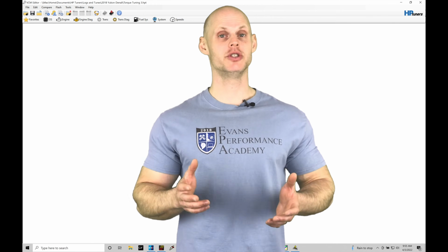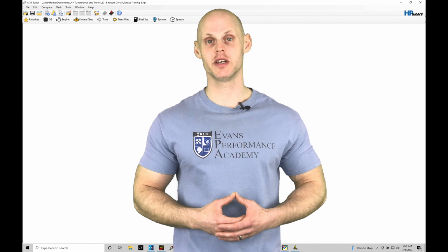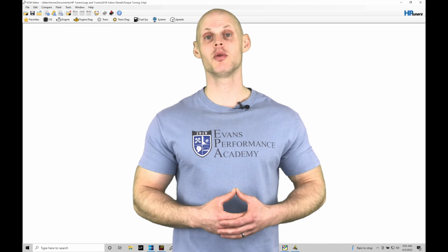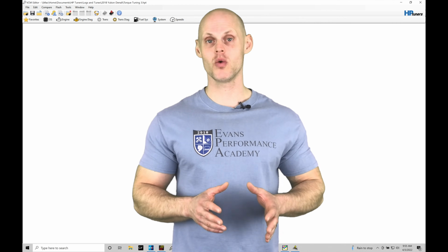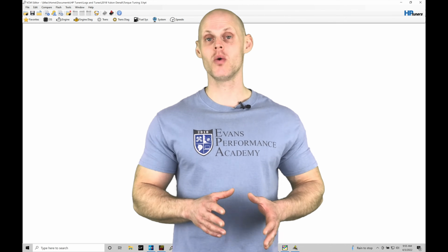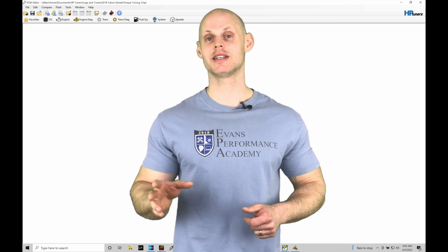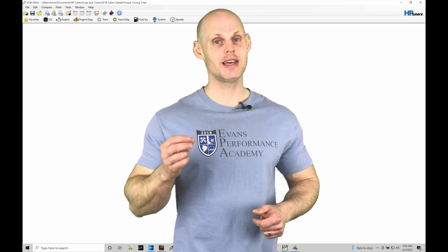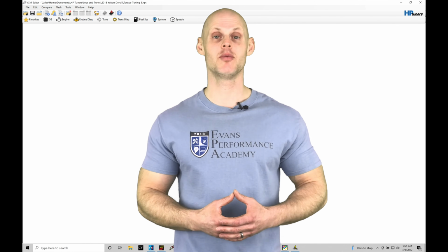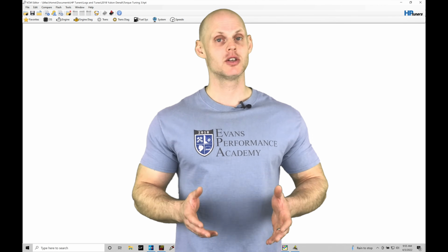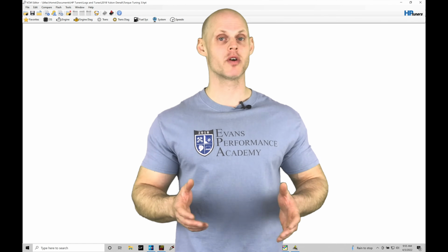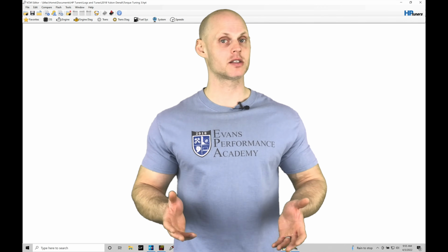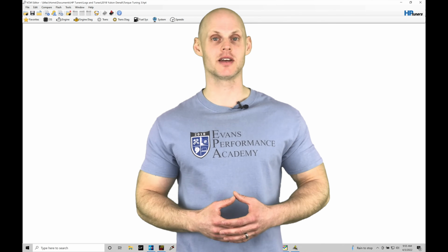Welcome to HP Tuner's GM Gen 5 Training Part 46. In this training module, we're going to be exploring how to dial in our airflow correlation tables so that we don't get a P0068 code thrown and that we can keep the failsafe protection feature enabled on our Gen 5 ECMs so that we don't have to worry about a runaway throttle situation. We have a lot to cover. Let's jump in so we can check this out.